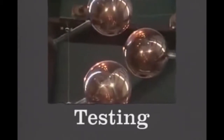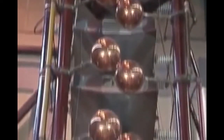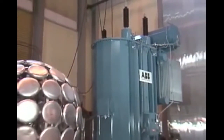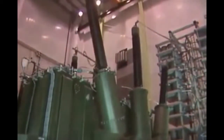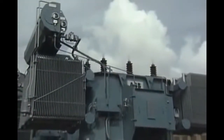A typical test sequence starts with lightning and switching impulse tests. After that comes an exhaustive range of other possible tests such as induced overvoltage and short circuit tests. All the accessories are also tested. In short, on every ABB transformer, we carry out whatever tests are required to ensure not only that the transformer meets the customer's demands, but that it has been designed and constructed to withstand conditions far beyond those it will ever face in actual operation. The transformer is now ready to leave the factory.